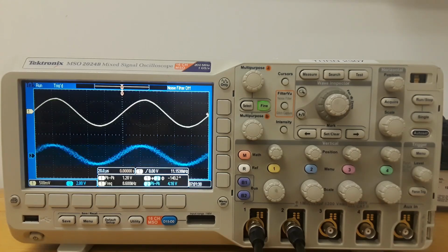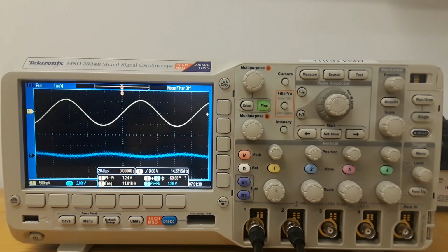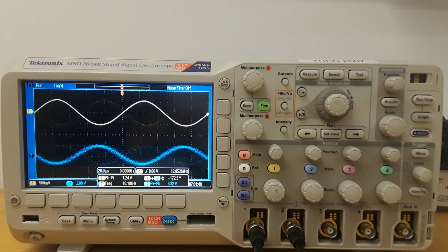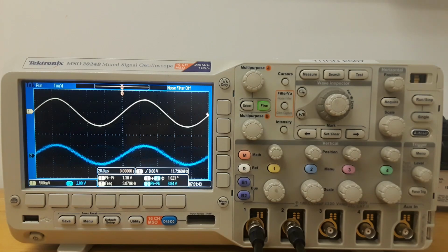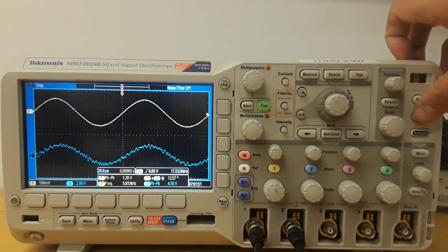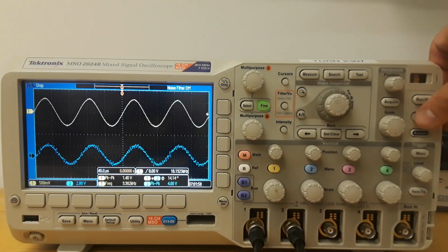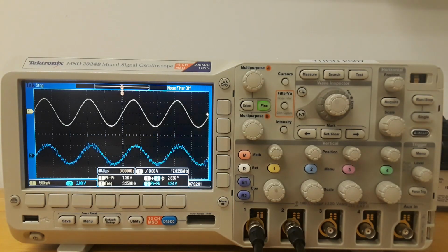It's a bit too low. But watch that oscilloscope as I turn my signal generator down past the 12 kilohertz mark and then go further down. There we go. We're right at 10 kilohertz there. And we take a look at our oscilloscope, hit single, and we can see again we've got a fairly adequate representation of our wave. Even if we zoom out and look at a wider angle view of it, we still see we've got our 10 kilohertz in and our 10 kilohertz out.